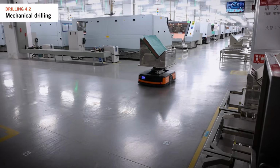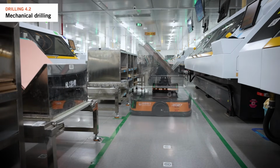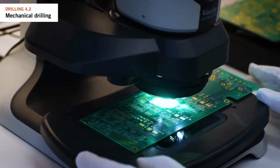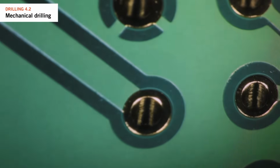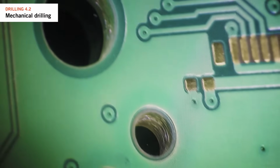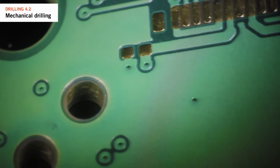Drilled holes are essential as they, once plated, serve two purposes. The first is to create electrical connections between all the layers, usually going through the entire PCB. This is called a via hole. The other is for solder through hole components. That is the component hole. There are also non-plated holes used for housing alignment and securing the PCB into its final product.